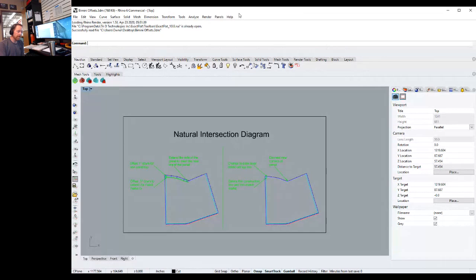So with the ProLiner, since we are patterning the entire boat, we preload the frames front to back. But then what we found works very, very well is we'll draw those frames, like the front frame, let's say, and load it down, put weight on it as if the enclosure was hanging there, installed, right? So forgetting to do that could completely screw up an enclosure that has a Venturi windshield that goes over, because when you go to install that, just the weight of those panels could drop the bimini frame a half inch, 3/4 of an inch or more. And then now you're going to add tension to that.